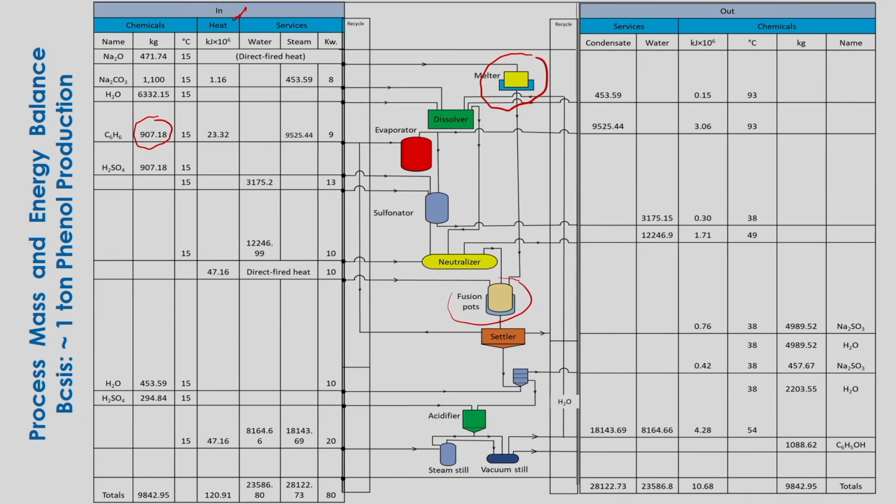In this way you can calculate for a specific chemical engineering process by identifying the different units and reactions. Based on the reaction stoichiometry, you find the input and output, and you have to calculate the enthalpy based on temperature change, that is sensible heat, and also latent heat if any compound is changing from its liquid state to the gaseous state.